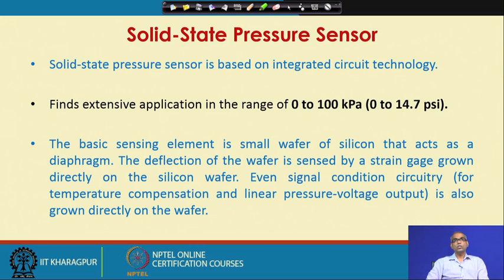So, the solid state pressure sensors are very advantageous because they have these distinct features. It is based on an integrated circuit technology and just consists of a small wafer of silicon, where you can grow the strain gauge or the signal conditioning circuits all together.